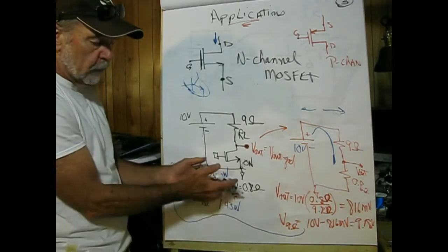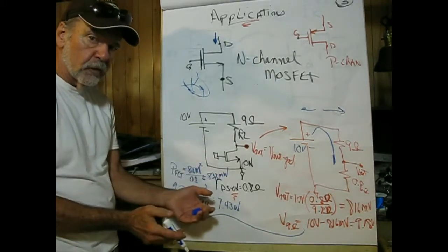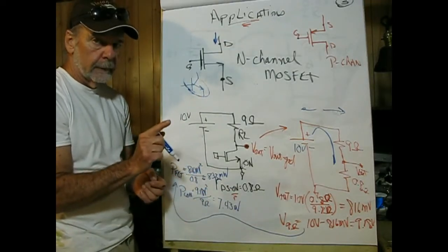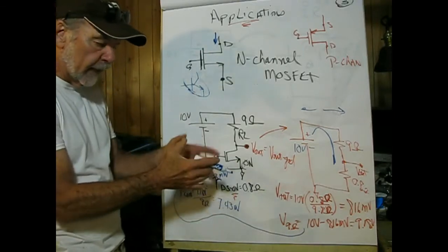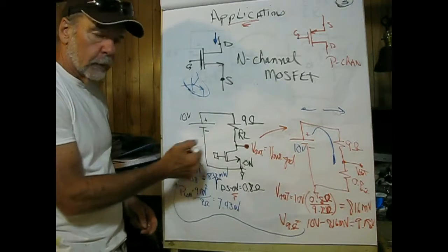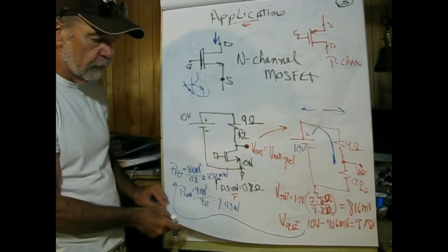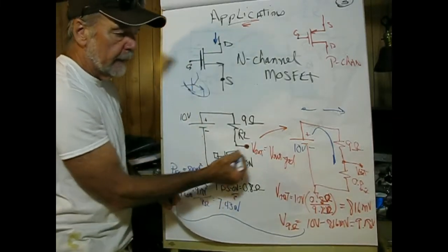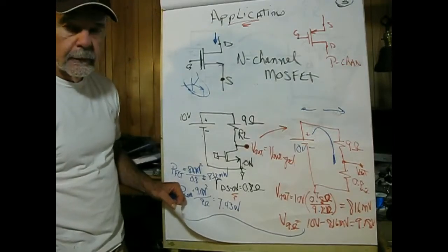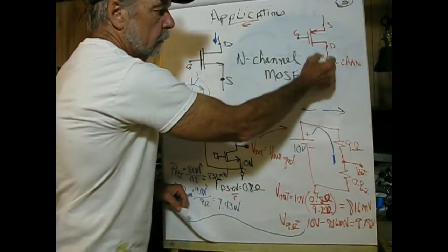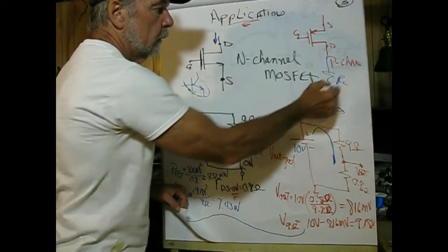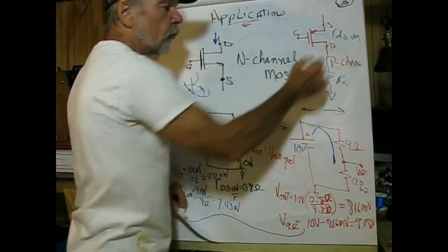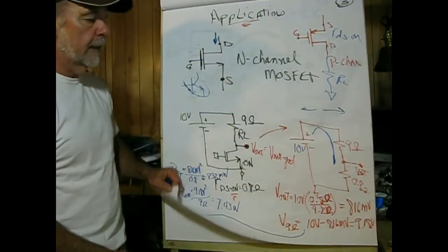What to keep in mind when we talk about power is if we have a 1/2 ohm resistor that's dissipating 1/2 watt, we can barely put our finger on it. So that's an idea. The larger the body is, the physical area, the cooler it in fact becomes because there's more radiating surface. So this is the way you would handle a FET DC switch, by decomposing it into its equivalent series circuit. And this could be high side too. This could be RL, and you treat this the same way. You have to be told what RDS on is for this part, and that's fully turned on.